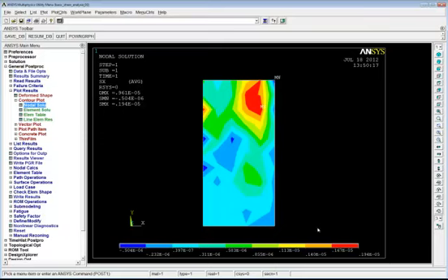But the thing to do is to always look at the values, okay? So it's telling me the maximum stress here is 0.194 e to the minus 5, so that's really negligible stress. So again, we can see a range of a compressive stress of minus 0.5 e to the 6 and a maximum tensile stress of 0.19 e to the minus 5. So really, there's no stress in there. Okay, this has just been introduced due to some computational problems in the finite element method itself. Okay, and again, we'll come back to this later on.